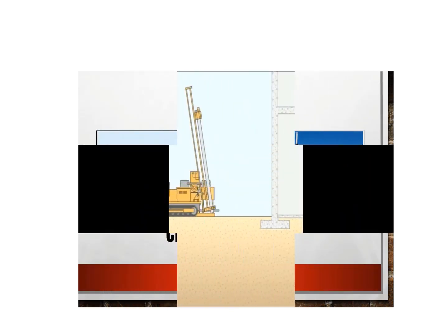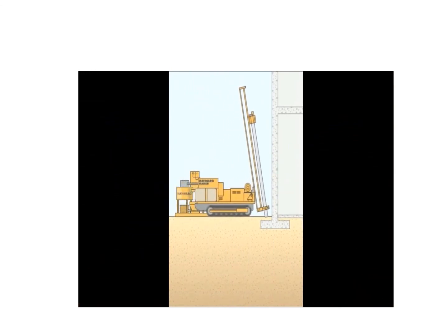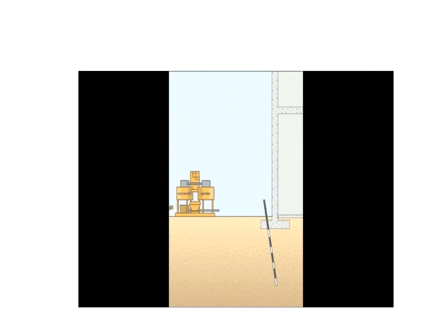And this is another type. Here they are injecting mainly for a foundation. If the foundation is weak, they can give it like this. Particularly for an isolated foundation, just giving. They are injecting the cement under the foundation to strengthen the weak soil under the foundation.